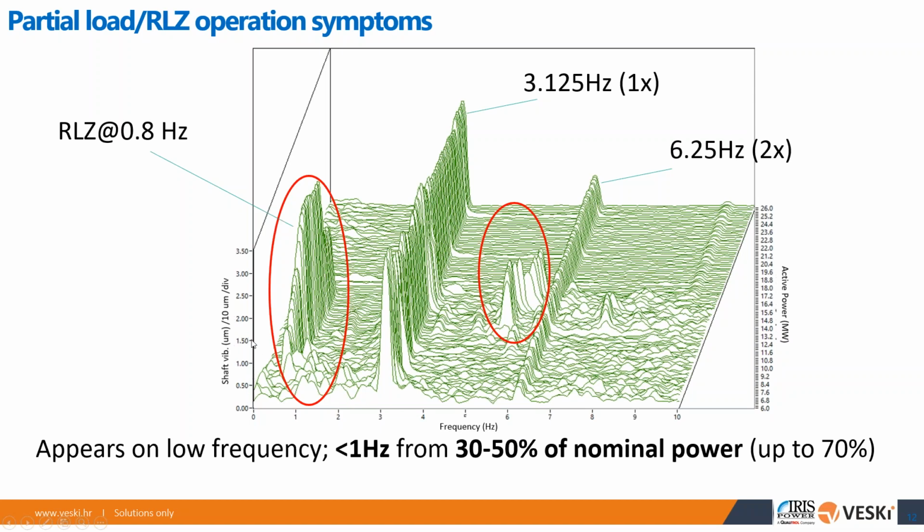Each of the marks on the y scale should be multiplied by 10. So this is 5, 10, 15, 20, 30, 35 microns. And in the power span from 10 to, let's say, 18 to 20 megawatts, this machine experienced the low frequency vibrations, and then they're at the peak at some 15 to, let's say, 18 megawatts.